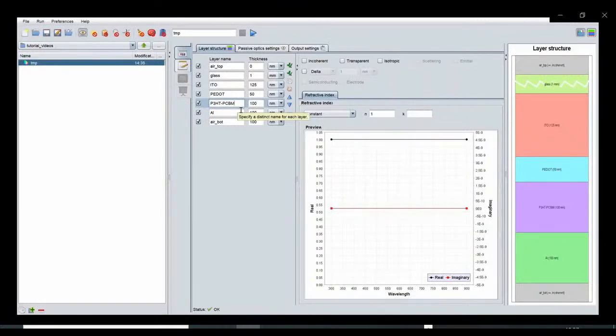the thickness of the absorber layer that produces the maximum short circuit current. For that purpose, we activate the absorption module. Now we have to define the optical property of different layers regarding the material constant and whether the layer is to be treated as coherent, incoherent, or even as a transport.